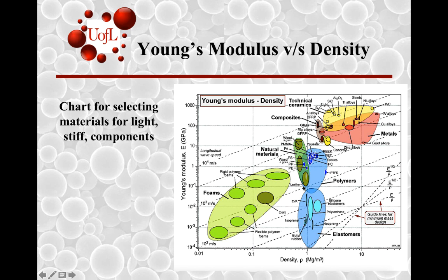Even within polymers, let's take a look at some natural materials. For example, wood. You would see that the modulus parallel to the grain has one class of properties in terms of modulus, whereas perpendicular to the grain, you end up having a distinctly lower modulus. So what does that teach us, for instance, would be useful to know. Also, you could see that within foams, there are larger property variations as there is a distribution of foam porosity size distribution and volume fraction.